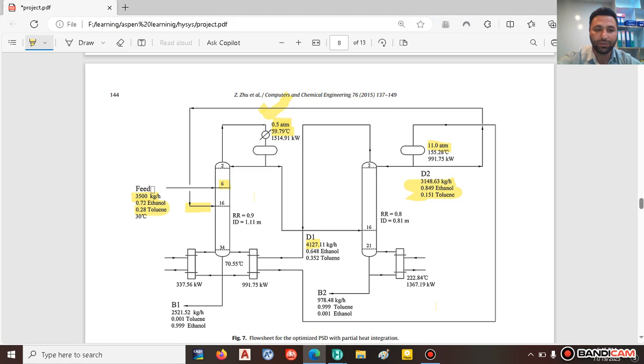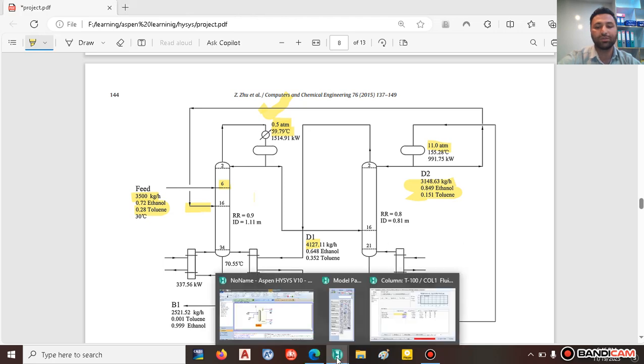Go to the PFD. We have 3,500 kg per hour for the feed and about 3,000 kg for recycle. So our distillation flow rate should be maybe just half of the sum of these two streams, which is equal to 3,000 kg per hour.